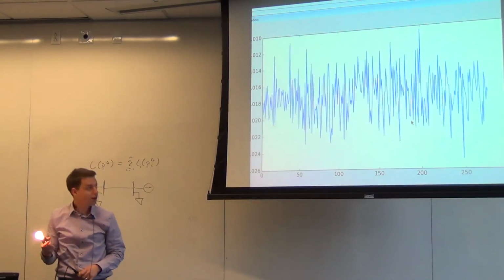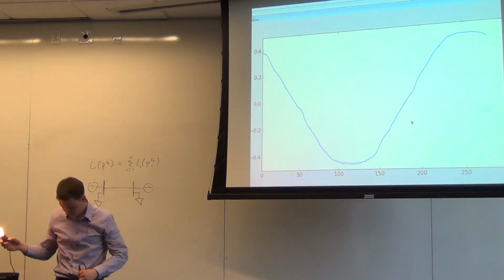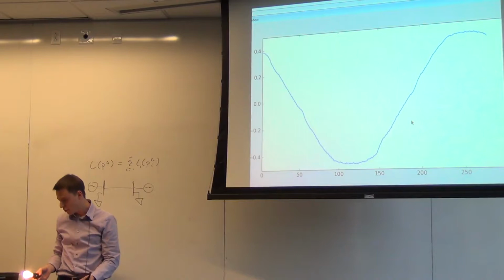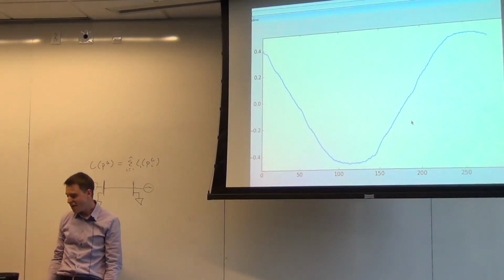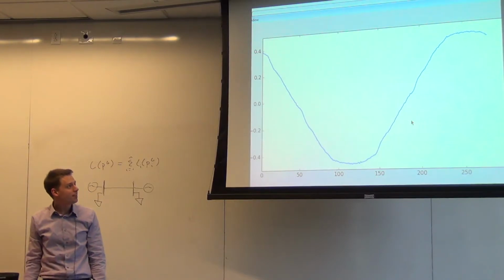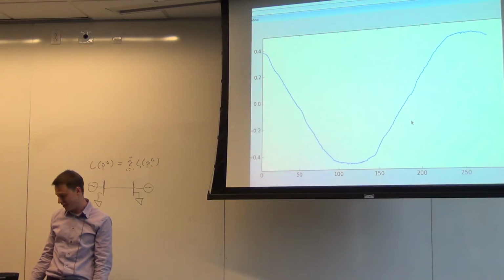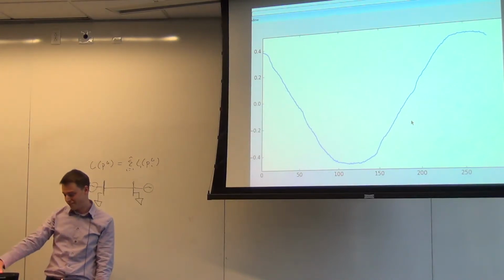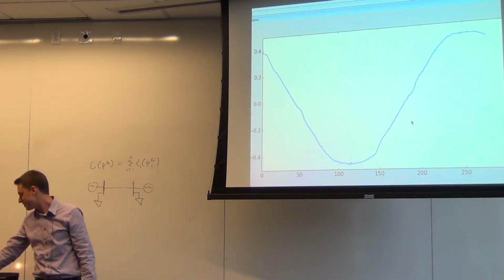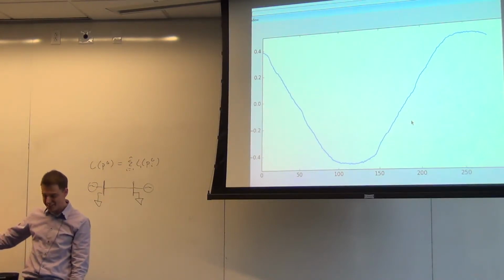We turn this light bulb on, and it's not very well. That's actually weird. Why is it doing that? Oh, never had this happen before. What's happening here is that these are actually on different phases of voltage. Interesting. Okay, so I'm actually aligning to a different phase here. So the voltage phase coming out of this thing is not the same as out of that one, because this is plugged into something behind that, and it's not the same as that one. I've not ever seen that before when I do this.